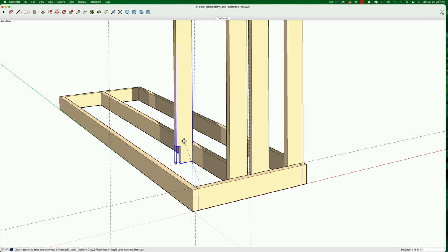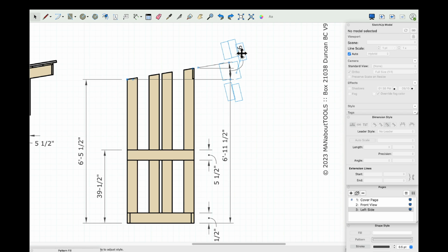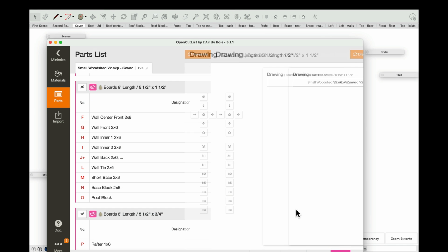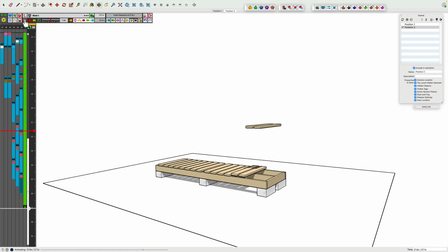In this episode, I'll take that 3D model and create a fully dimensioned drawing from it, with all the views and details required to build it from standard nominal framing lumber. I'll also make an automatic cut list from a SketchUp plugin. Finally, I'll use another plugin to create an animated sequence showing the shed being assembled.